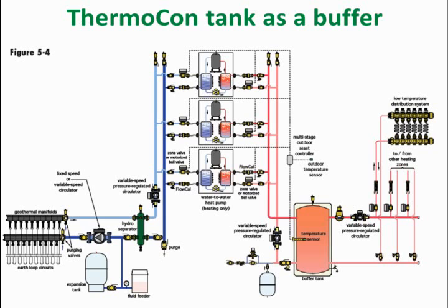And now what we've done here is we've shown you this with the hydro separator. Let's call this a single pump system. So we're taking a single pump and then we're bringing these heat pumps on with electric zone valves here. So if one is calling, this zone valve opens and it gives it the heat. In this case, we're showing it in the heating mode. You can see the red tank over here indicates we're in the heating mode. And then as more heat's required, they would step in like that. We're also showing one of our flow cals here, so we know that every one of these gets the exact amount of GPM flow rate that it needs. We'll put a flow cal on that line to the heat pump, and of course little isolation valves and some purge valves and stuff here.